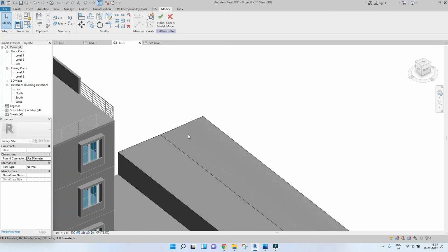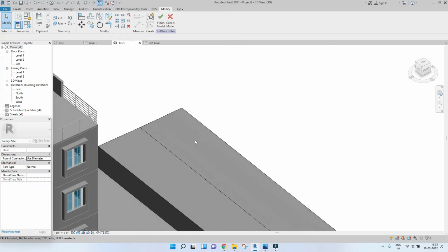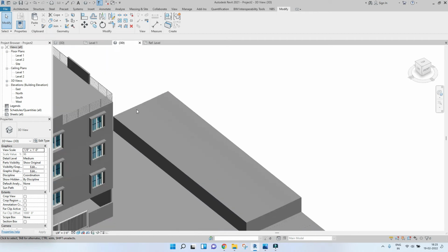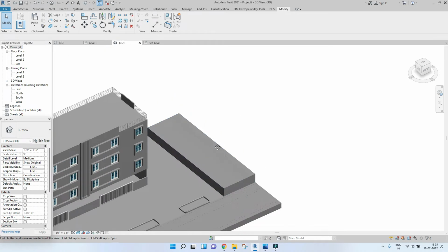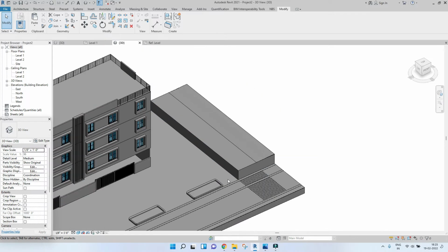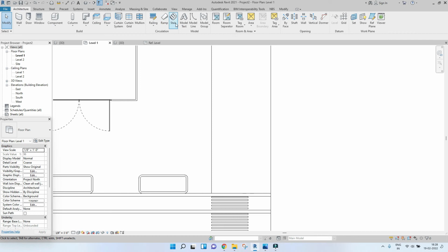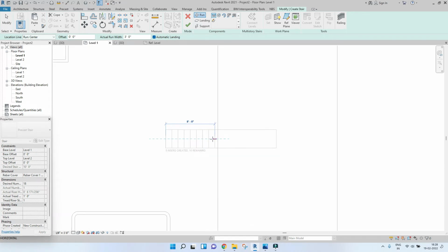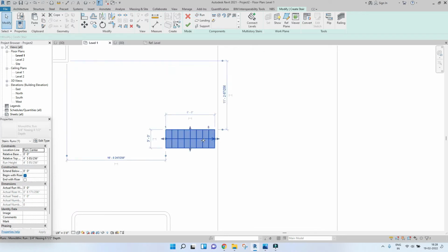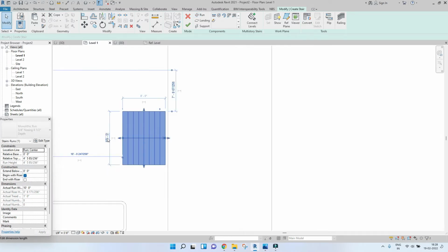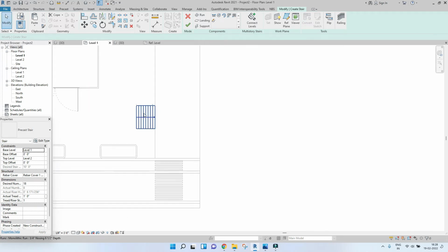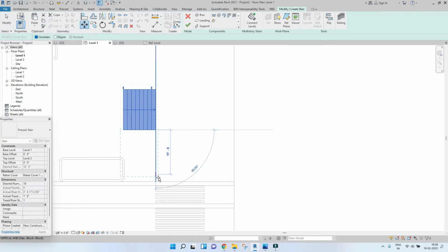And then over here we'll be adding some trees. So just click on finish model, and we've created the block, and this is where the sidewalk will be. And then right in front of this, let's create stairs by going to the stair option and select the precast stair, and let's give 8 risers. That should be enough, and change the width to 10 feet, and make sure it is aligned to the end of this block, and move it to this end.